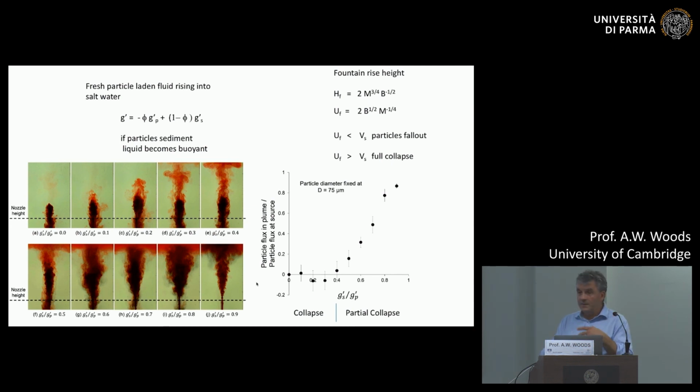And you can see there's some very complex relationships, but ultimately the critical number in all these problems is the ratio of the convective speed of the bulk mixture compared to the fall speed. And as you move through that from being greater to smaller than 1, the overall structure of the flow can change quite fundamentally. And I think we've seen that in a number of different examples.